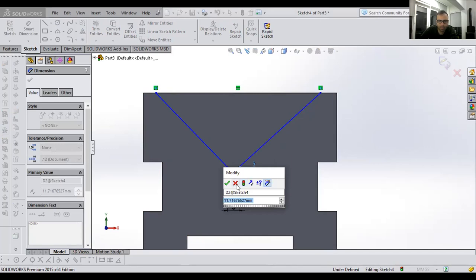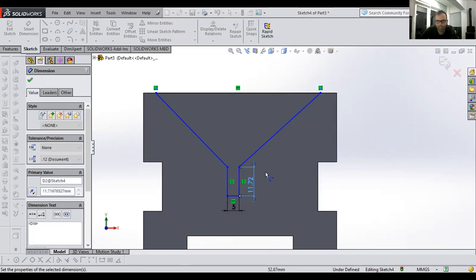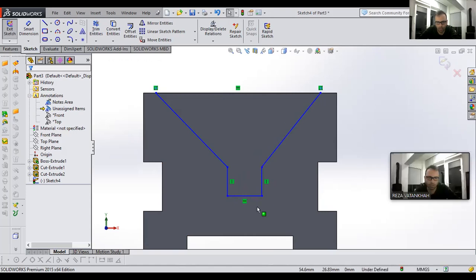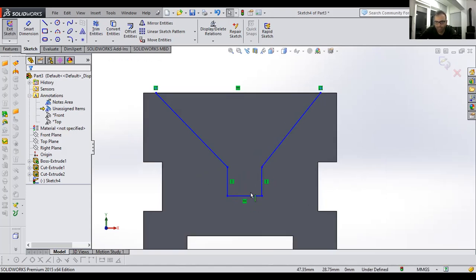When you have a complex sketch like this, try to put dimensions from small to big, okay? So be careful. If you have small dimensions, it might be better to put the small ones first. Otherwise the figure will be modified, okay? Let's do it. Look, you can delete the dimensions, select delete.